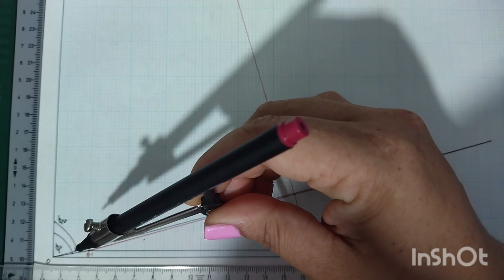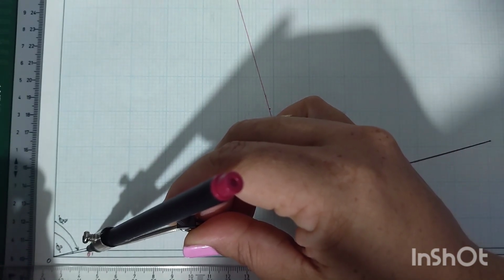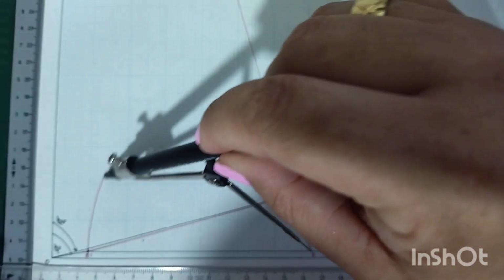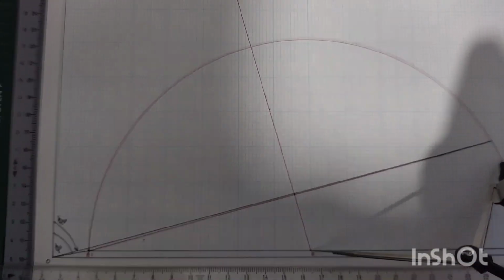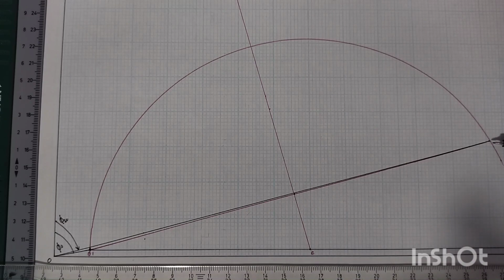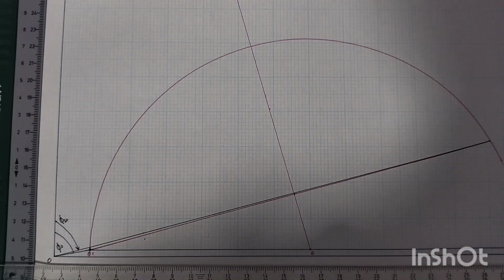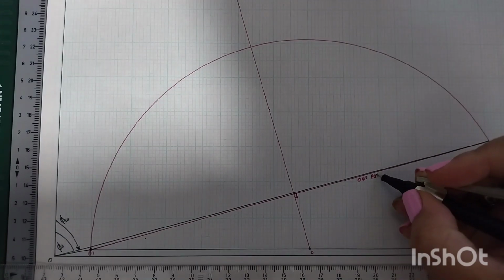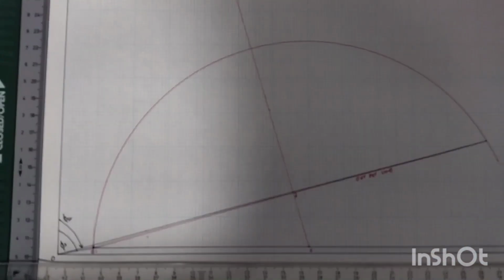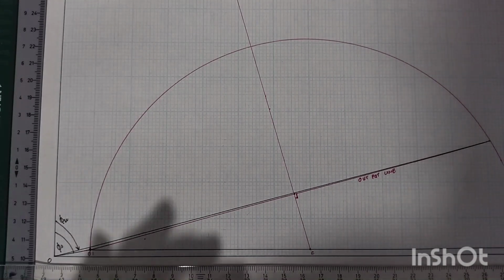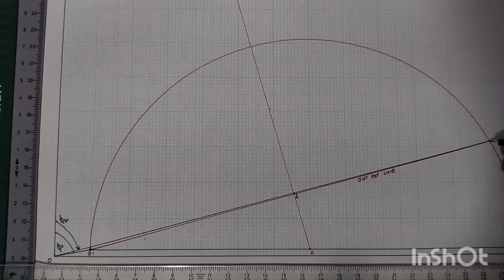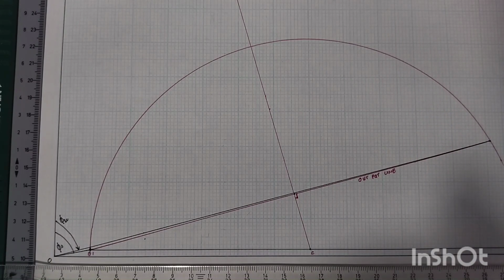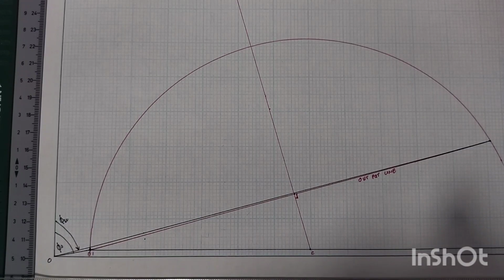Here I had a little trouble with the sound, which may very well be a blessing. So at this point, you have to construct your circle. Of course, like I said, O prime to C, C for the center of the circle, is your radius. And you'll see that that line meets the end of your short circuit current. Just to indicate that that is perpendicular over there. And then again, that is your output line, that is your power. So everything above that line would be the output of your motor at various loads. If I bring your attention right to the end there, that would be your reading at standstill or at starting.